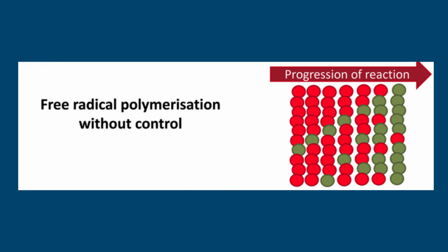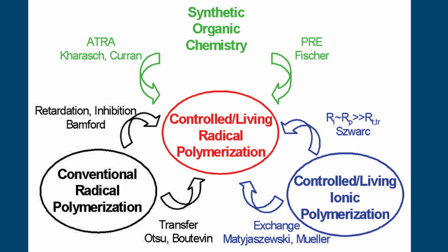Conventional free radical polymerization provides limited control over molecular weight distribution and sequence architecture because growing radicals terminate irreversibly through combination or disproportionation. Over the past 3 decades, controlled/living polymerization techniques have revolutionized copolymer synthesis by suppressing irreversible termination and maintaining active chain ends throughout polymerization.